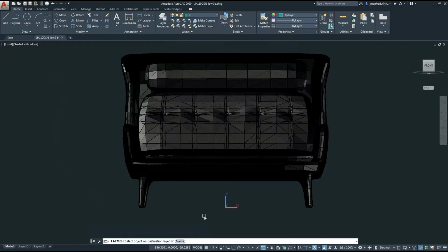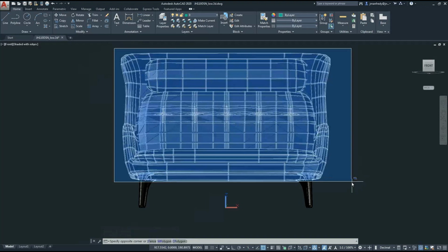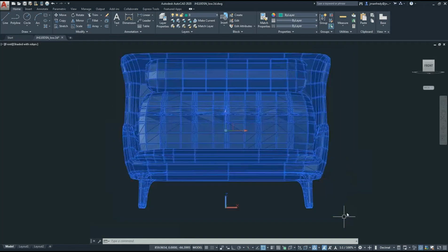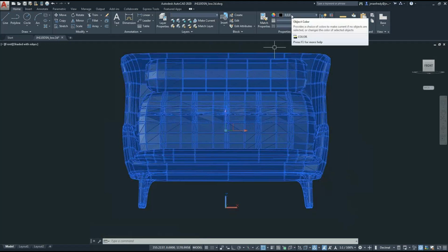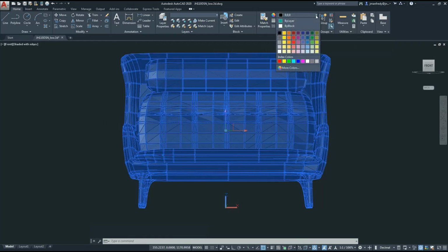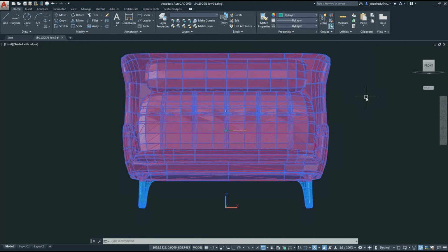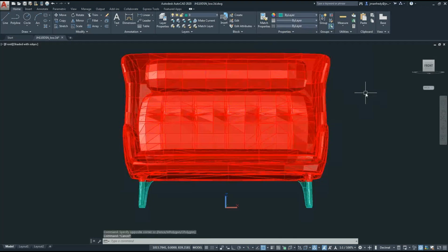Now you'll notice that the objects are still this sort of black color instead of the red color that I've assigned to these polygons. So another thing that needs to happen here is when you select all the objects here, you'll notice that the colors by default have been assigned to object color black, which is 000, when in fact they should reflect what layer those objects are on. So flipping this to by layer tells the polygons colors to be assigned by the layer they're on. Hit escape. And for example, these turn red because the layer that I've assigned them to is 3D frame.